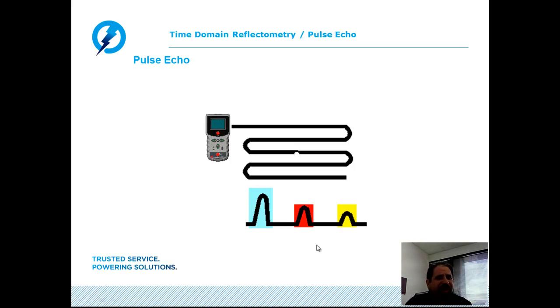Instruments performing the pulse echo technique, typically referred to as time domain reflectometers, make it possible to see into a cable, giving us the ability to visualize or detect different cable landmarks such as splices, transformers, cable transition areas, for instance like buried cable to aerial transition, etc. In addition to this, it also gives us the ability to locate the start and end of a cable,